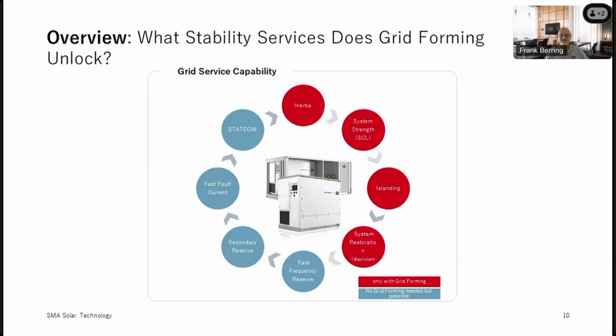Good. Next question from Cameron Cruz from KIOC. While in grid forming mode, can the inverter be programmed to output negative sequence current, magnitude, and angle? I believe the answer to that is yes. Lucas, would you mind? Yes. Yeah. We do provide negative sequence even in grid following mode, and it can be provided in grid forming as well. So that's something we have proven over time in models and real projects as well.